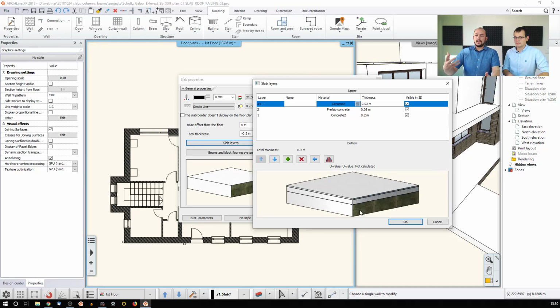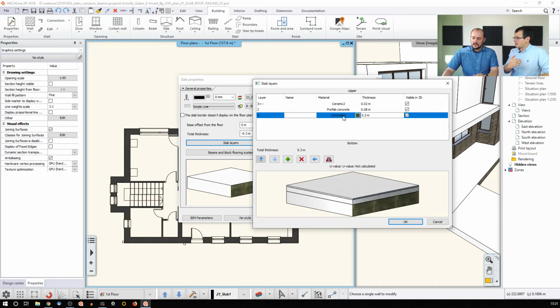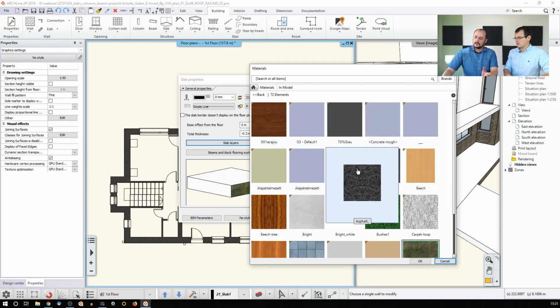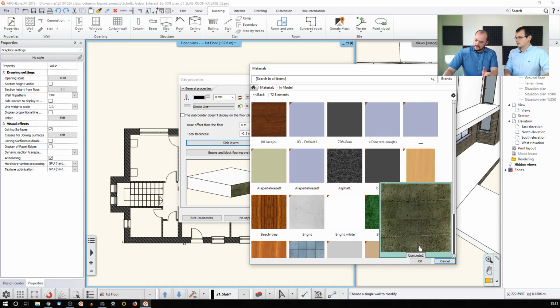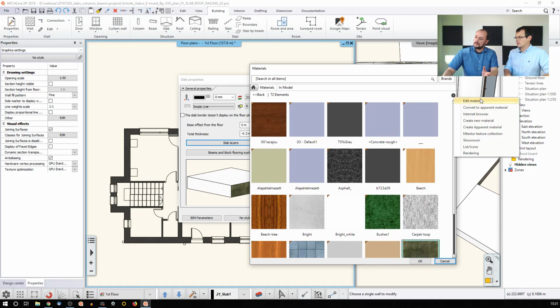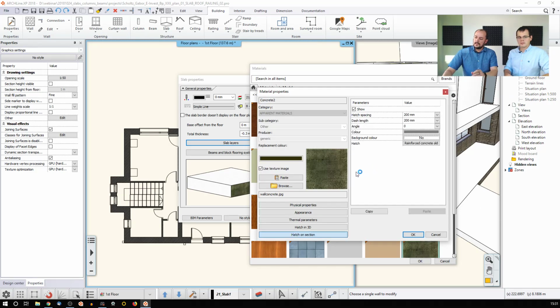And this is the way you can define how it will look when you do the regular architectural section. Materials define how the architectural section hatch looks. Oh, so you don't have to set up the hatches one by one. You just have to set up the appropriate material, and that would govern how the two-dimensional... Yes. If you would like to see how that works, you just select the concrete material, go to the edit material options, and then you will have the setting, the hatch on section.